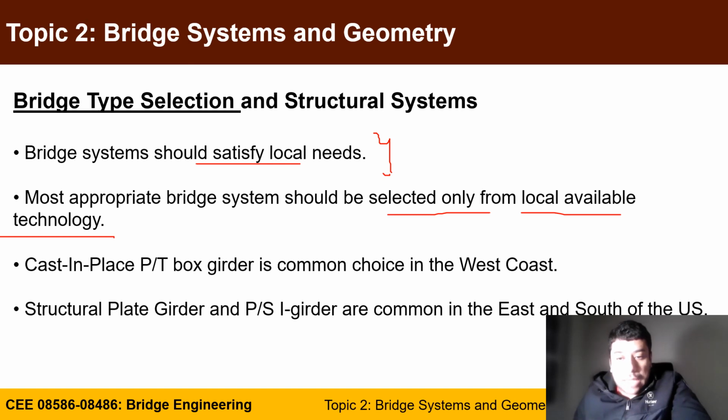In the last topic, we put a big emphasis on accelerated bridge construction as a construction technique, from prefabrication to bridge slide to SPMTs. But if you don't have that technology within your state, plus you don't have experience from contractors, you should not import it from another state, because it will be much more expensive and cause problems. This is not meant to hinder the implementation of those technologies, which can be built at a pilot scale, but in general, you should use locally available technology.